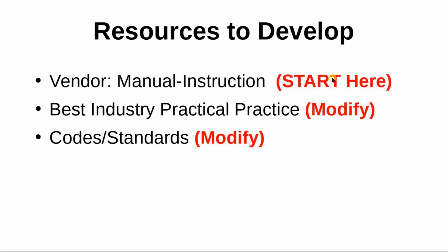Where to start? Your starting point is the vendor instruction manual. Then you have to modify it to suit the application. First, you look at the best industrial practice, and see if you need to modify it. And this is very important, to look at the codes and the standards if you need to add or remove something from the manual instructions.